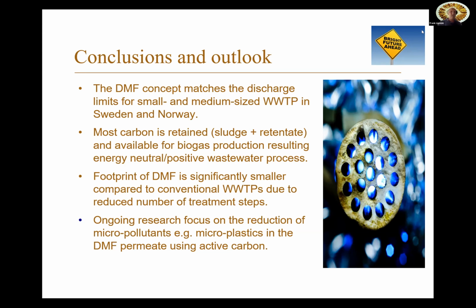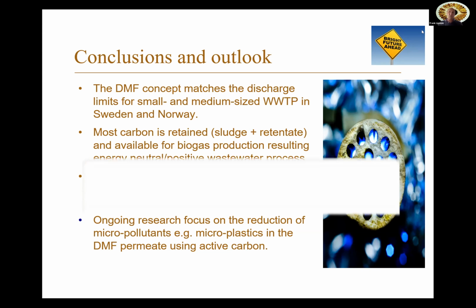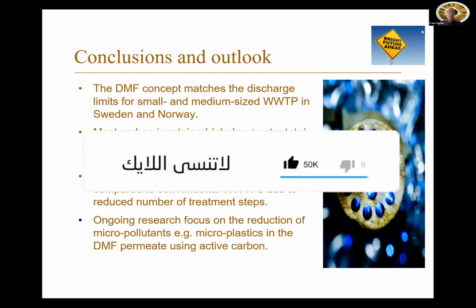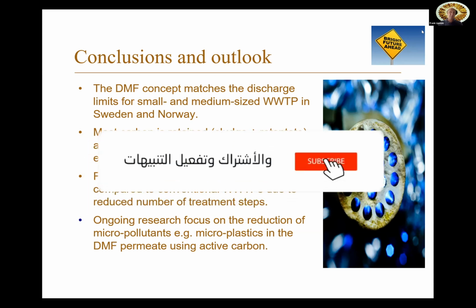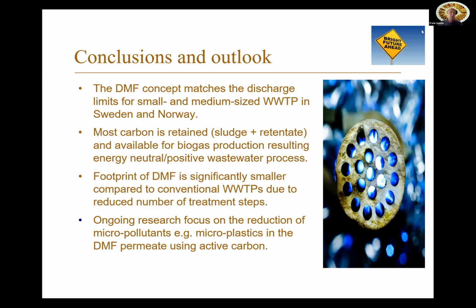Furthermore, when you compare the footprint of the direct membrane filtration plant to a conventional wastewater treatment plant, it is significantly smaller, and the number of pre-treatment steps is also reduced. Our ongoing research now focuses on the reduction of micropollutants, for example, what is the fate of microplastics in the direct membrane filtration permeate when you use activated carbon as the final step.